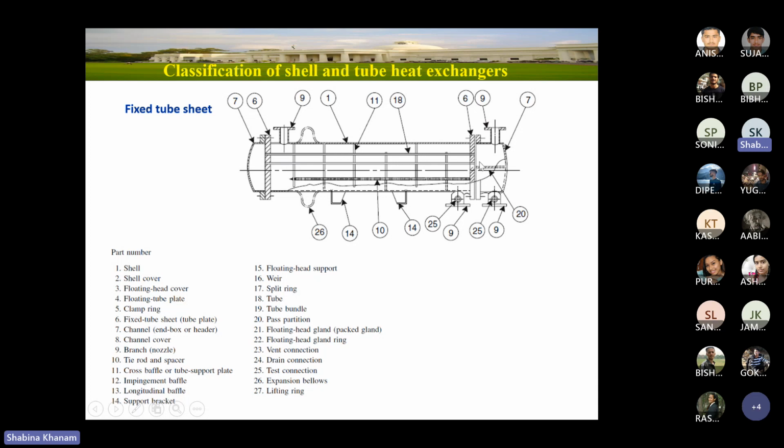And here, if you see, there is no partition plate. Partition plate will be available here as well as here, but not in between. So fluid will again enter the third 1/4 number of tubes. I hope you are getting my point. Okay, and then it travels the whole distance, and then here no plate is available, so fluid will enter the fourth 1/4 of tubes, right? So it will enter from here, travels the whole distance, and then exits from here.